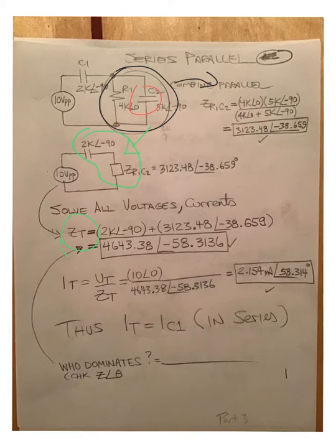Once you get that, we go down and we compute the total current using Ohm's law. Very straightforward. And then we reflect. And we say, hey, we've got the total current. What does that mean about C1 up at the top? That capacitor, that gets all the current. That gets IT. We could actually calculate its voltage on the next page.